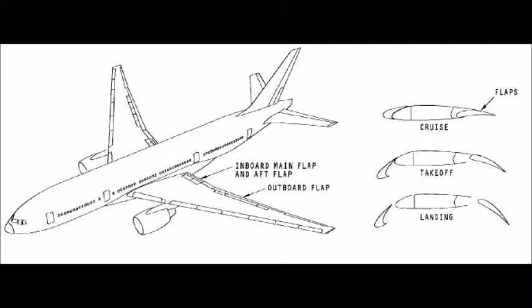Flap operation. The flaps operate in sequence with the slats. At cruise speed and altitude, flap extension is inhibited. The load relief function retracts the flaps to prevent structural damage to the flaps at high airspeeds. The flaps are monitored for skew or asymmetry. When the system detects a skew or asymmetry, the flap drive shuts down.